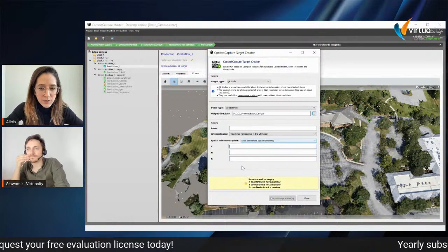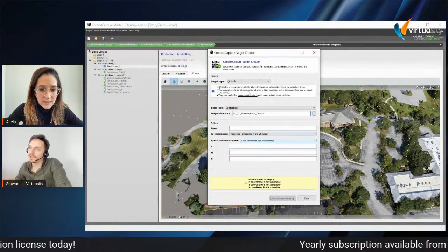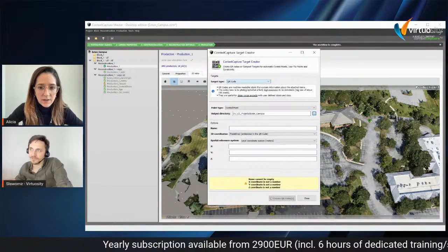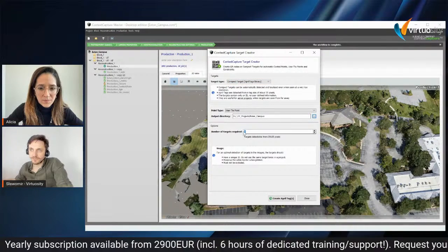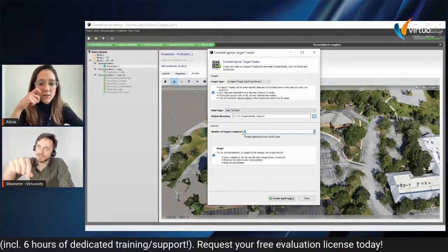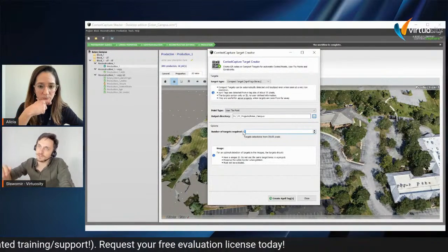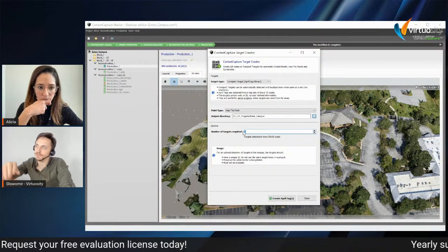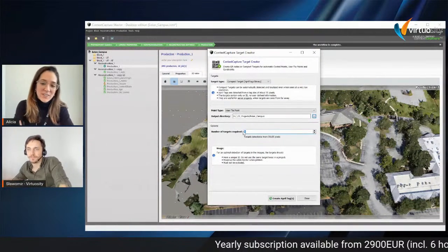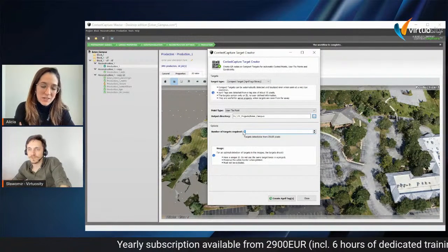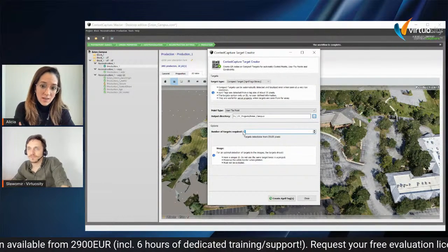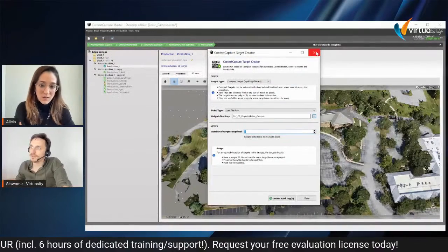So what's the difference between the QR code and the April tags? Is it the coordinates? In here, you can put much more information. In case of an April tag, you can put only a number. But then if you import the numbers correctly, the same file list with numbers and the correct coordinates, they're going to fit to each other. So they will be already found. So it's just one step. Basically, the April tags have one step more after the processing: during the processing, you will have to match the numbers with the coordinates.